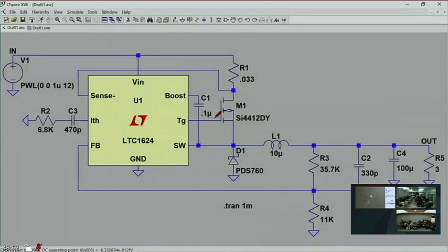Now, think of the gate driver as a 4-terminal device: input, output, power, ground. The input is connected to the controller. This particular connection is not bonded out, and since you don't know what potential this thing is at, let's assume it's differential. The other 3 pins are bonded out as pins.